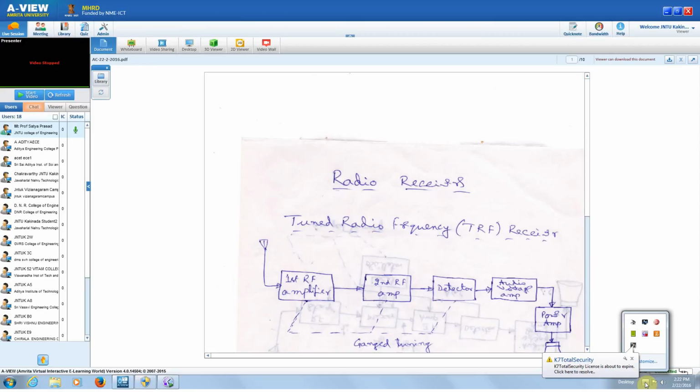Compared to a single tuned circuit, a double tuned circuit gives more elimination of the unwanted or adjacent signals, but tuning all these circuits in a ganged way for all these amplifiers and the detector with double tuning is going to be a difficult proposition,